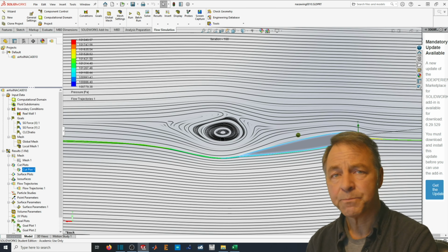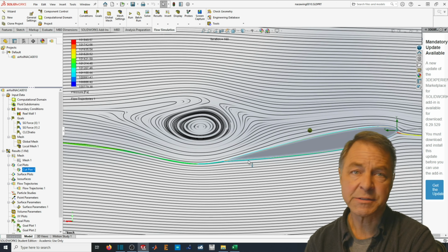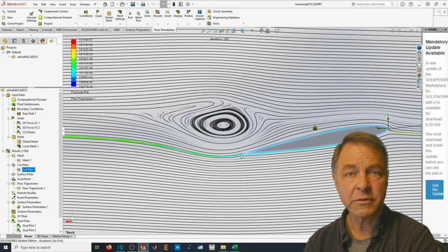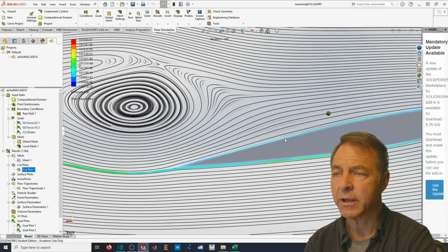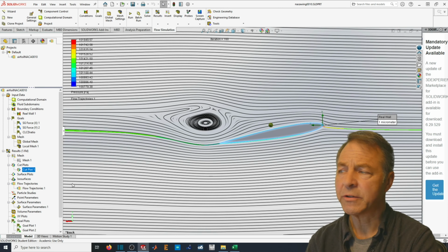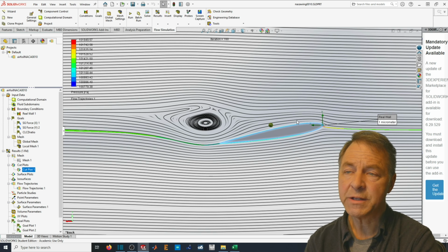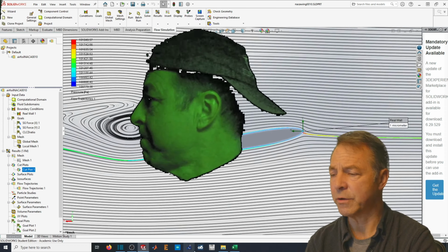Well, this is a case where we're trying to ask a computational tool to simulate a very difficult physical phenomenon, which is the boundary layer and the behavior at the boundary layer. Now, if we could look at this simulation in real time as it moves, we would see that with each successive iteration, the location of a separation point on the surface of this wing would be different.